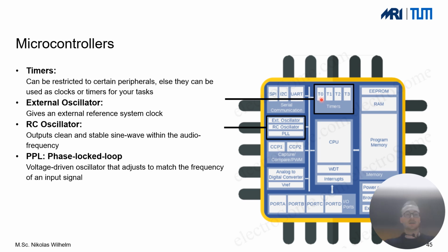Next, there are lots of things happening in this single microcontroller unit. We also have the timers. They allow us to, for example, follow certain frequencies where we have an exact clock being set from these timers, and we can then manage our external sensors with that respective clock signal. So we have a frequency on which we want the signals of the sensor to appear. And for these timers to be very exact, usually development boards such as an Arduino have external oscillators. So they get an input signal from such an external oscillator.